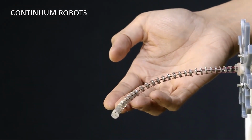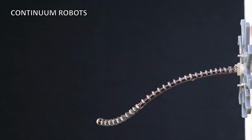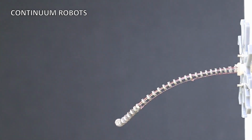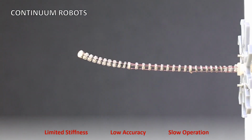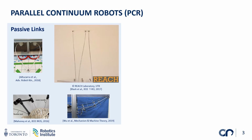However, there remain some challenges arising from the inherent characteristics of continuum robots that make it difficult to realize the envisioned application areas, such as their limited stiffness, low accuracy, and slow operation speed. To this end, parallel continuum robots, or PCR for short, have been proposed, which aim to find a compromise between the compactness and dexterity of continuum robots and the strength and accuracy of parallel robots.